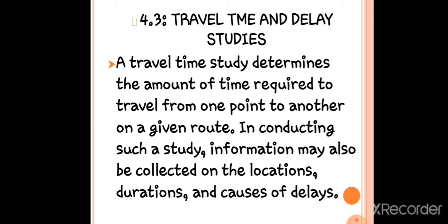Data obtained from travel time and delay studies give a good indication of the level of service in the study section. This data also aid the traffic engineer in identifying problem locations, which may require special attention in order to improve the overall flow of traffic on the route.